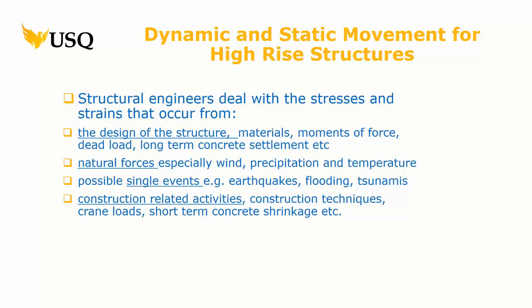Obviously, earthquakes are well documented, but you can't tell when they're going to happen. That's the biggest issue. And then construction-related activities. This is the one that, as students, you don't think about, but if you're working in real construction, construction causes its own problems. When you stick a crane on one side of the building, it makes the building lean. You put a load on the crane, and it moves more.